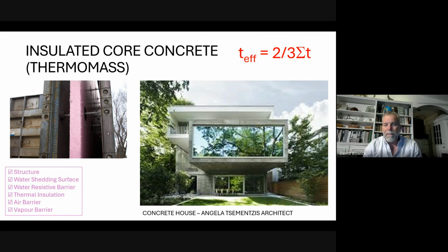It is a vapor barrier. I think the rule is that 2.5 inches of concrete is thick enough to be an effective vapor barrier. So we're not worried about vapor migration through this. There's enough thickness. Also, where's the vapor going to go? The insulation, your dew point is going to lie in that insulation there. It is a closed cell expanded polyurethane. The dew point can be there. It doesn't matter. The vapor can't migrate into the polyurethane.